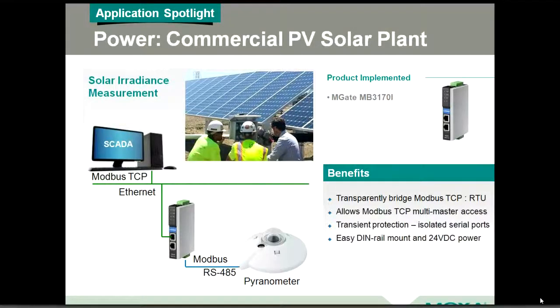The only way you know about that is by being able to know how much power is being sent to you through the sun and how much is being produced. So you might use something like a pyranometer here to measure solar radiance, and by knowing here's how much we should be receiving and here's how much we're producing, you can find out that there's a problem within your system. That could be dirty solar panels, it could be a number of things.